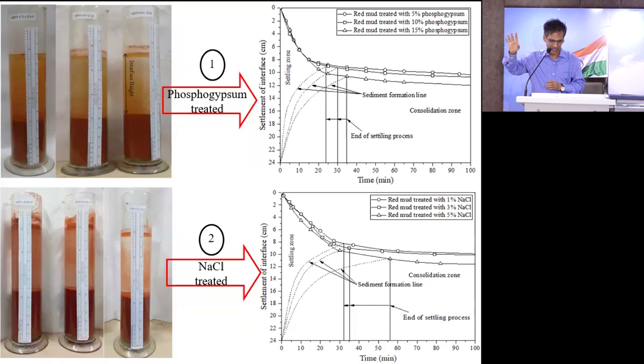Hazardous to, I think one hazardous you can say, when pH is there. That is what experiment I did once. When I tried to use red mud in 2009 or 10 to just characterize, I had an idea that earthworms, you know, earthworms convert the soil. I said, people are not using, let's put some earthworms. Earthworms will convert it naturally. All of them died within 1 week. The problem is they cannot survive in high pH. Similarly, no grass will grow on high pH. So when you are talking about hazardous, you have to see where it is the problem.